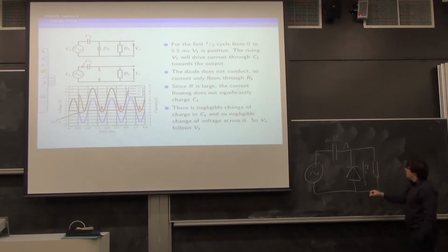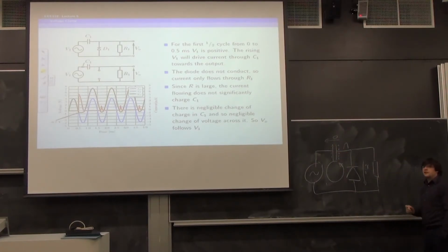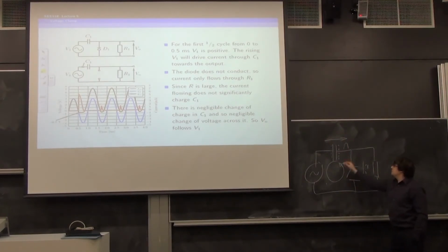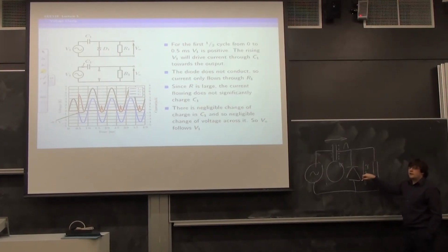And once we've got that, we'll have some current flow around this loop, and charge will accumulate on this capacitor. And you could say, all right, some charge has to leave this plate as well, but how you want to think about it is neither here nor there. Some current flows into this capacitor and is stored as charge, and that results in a voltage appearing across it in this direction, because this is the plate which is more positive. And that voltage will rise up to whatever the input voltage is minus the value of the diode.